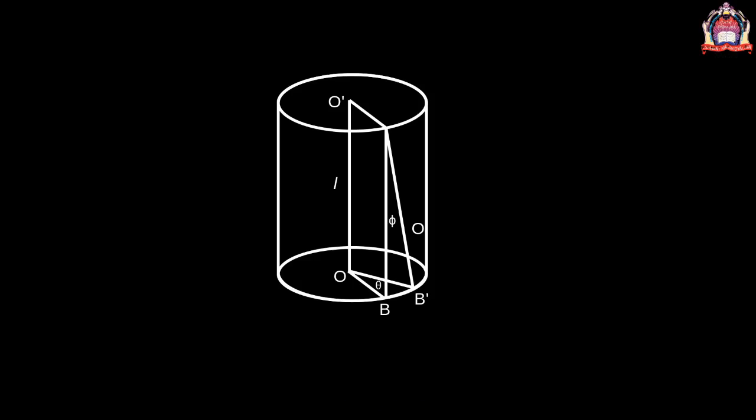Its upper end is clamped and the other is twisted by applying a couple to its lower end in a plane perpendicular to its length. The rod is said to be under torsion. A reaction is set up due to the property of elasticity, and a restoring couple equal and opposite to the twisting couple is produced. All the particles in the lower end are shifted through the same angle theta, but the linear displacement of a particle near the rim is more.